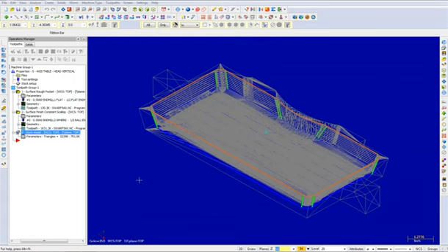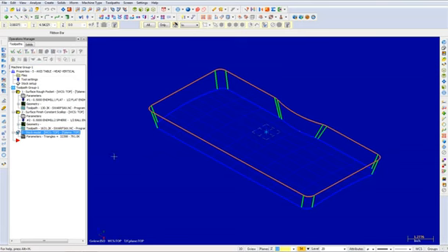In this video, we will create a Swarf toolpath. A Swarf toolpath cuts the walls defined by surfaces or chains with the side of the tool. To be able to disable the view of our stock model, ensure it's the only thing selected and click on the toggle toolpath display here.